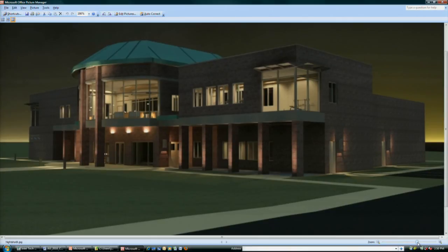And that was another thing I put in the notes as a general rule of thumb. Even though Revit has mental ray in it, we always have problems where we do an interior, exterior shot where the sunlight coming in through the glass just washes out the rendering. And by the time you adjust exposure control, you've made the image so grainy it's unusable. So it's not that Revit is inferior because it's using the same rendering package. What it is, there's no control to get to it.